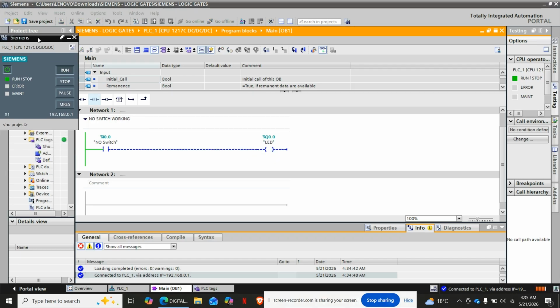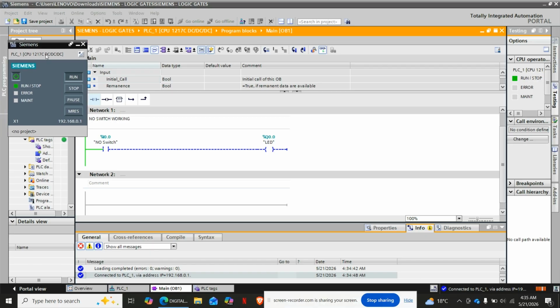We close the switch so as we have an LED on. So how do we monitor that? So click on this, come to this PLC sim and click on this one, switch to project view, right? So as to toggle the switch options. Now here we see that the switch has no input, so the input is 0 to the normally open switch. That's why the output is also 0. If the input is 1, which is high, then the LED will be 1.